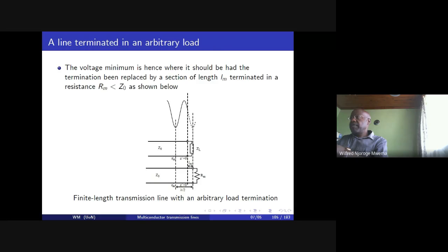And therefore we can, as we have seen, when you terminate a transmission line with a load or with a resistance, look at the input impedance at the input of the line, and we'll see that the line will have transformed whatever the resistance, the termination, into a new input impedance, which you can always say will represent the ZL that we have for a particular case.